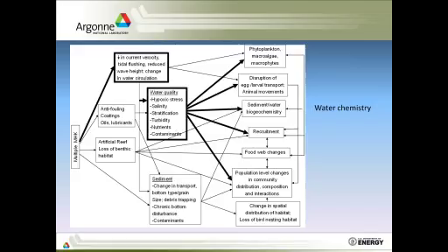And these kinds of things can, again, affect biota, so you can see a shift to more hypoxia-tolerant species. Salinity is very important in determining the distribution of fish and invertebrates in estuaries. So if you alter the salinity regime, you could change their distributions. Important for egg and larval transport as well. They use these tides, and they use water column stratification to transport themselves to their nursery grounds.